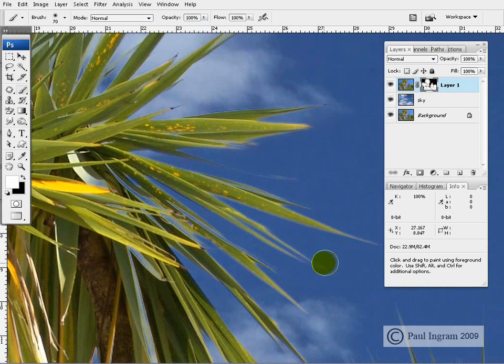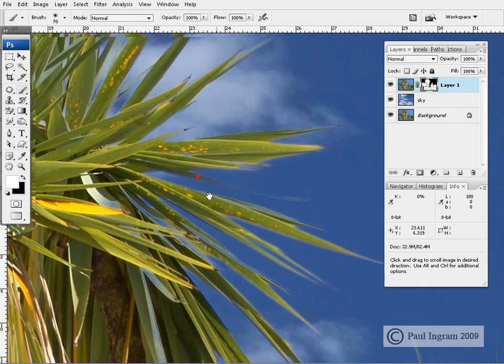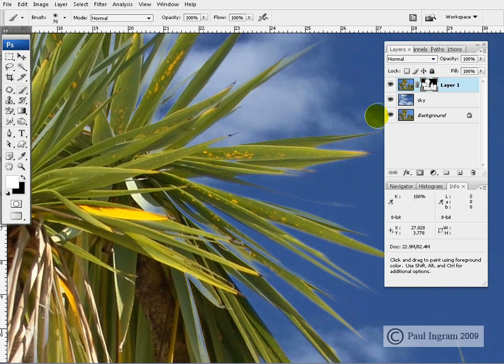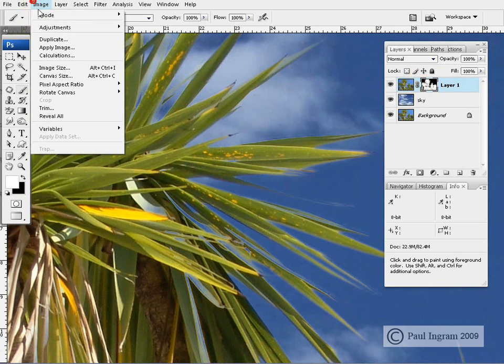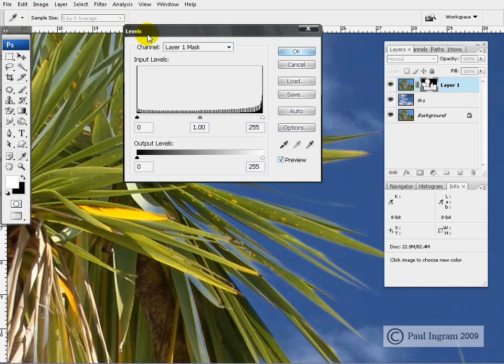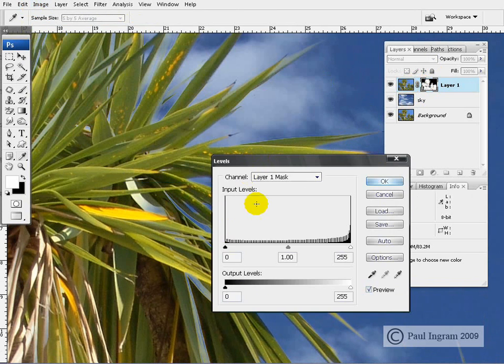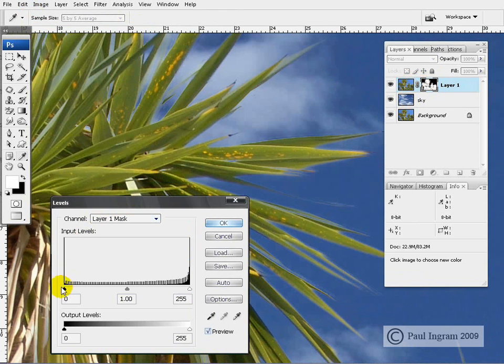If you're worried about some of the edges again with these images, if you feel that some of the edges are showing signs of not being quite so tight or not being as precise as you want, then don't forget there's the mask. Again, we can choke the mask with a further levels adjustment, so we can either pull it this way, maybe not so much, and you can see that's got rid of some of the very slight feathering across the edge that was going on there.